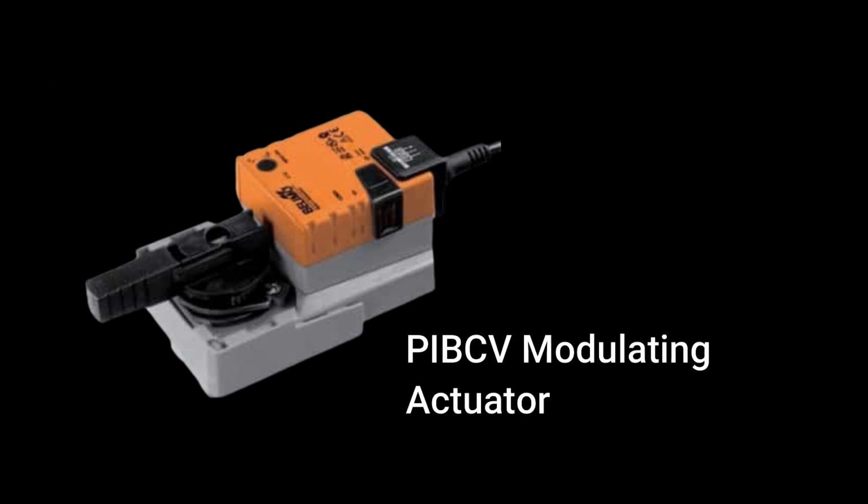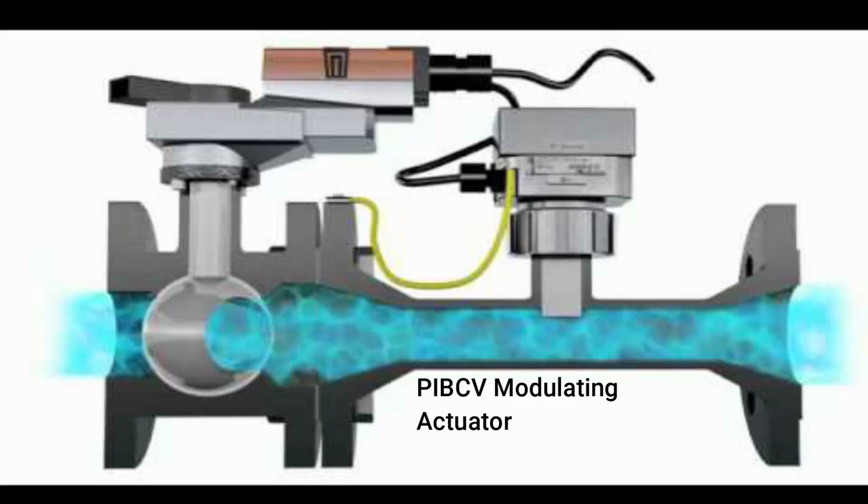Pressure independent balancing and control valves, or PIV-CV, modulating actuators are used for the PIV-CV of chilled water, air handling units, and fan coil units. As the name suggests, PIV-CVs are pressure independent. Hence, they perform much better when it comes to precision control of chilled water flow.